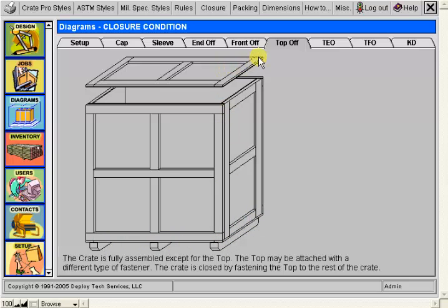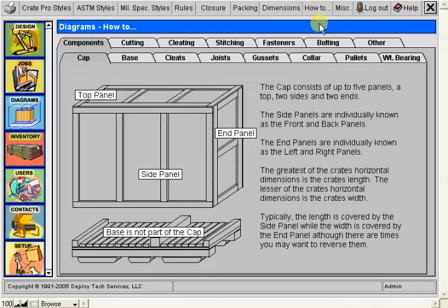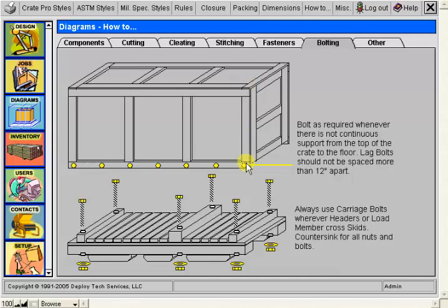When you put this cap on with an alternate fastener, let's go back here and take a look at this again. In this case where we put the cap on, we would be using an alternate fastener across the bottom, in this case a lag bolt, and let's say that we would place those lag bolts 12 inches apart. If this were the case, we'll still say 4 inches up and down here, then our nails here would have a factor of 1, because in the setup file we say we place these 4 inches apart. The nail we actually place 4 inches apart, so we have a value of 4 times a factor of 1 equals 4, which means there's a nail every 4 inches.